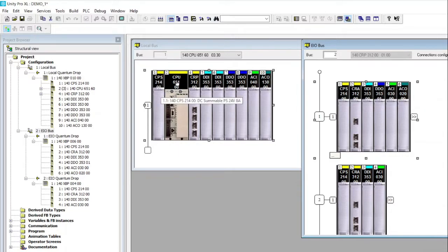So now we need to transfer or download this configuration to our physical PLC, which brings us to the connection interface, which was the second section of PLC theory. In this case, since we are on the programming software, we're going to set up the connection interface in software. At this point, your PLC needs to be physically connected to the engineering workstation, whether it's serial, USB, or Ethernet.